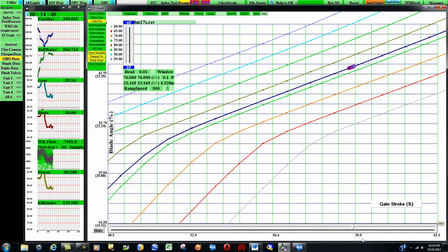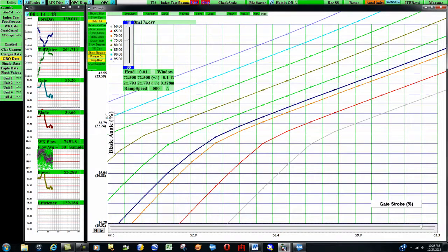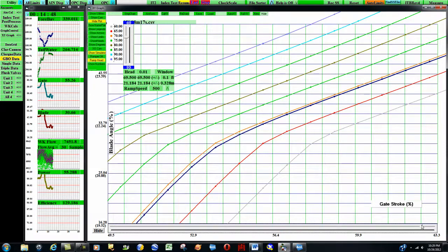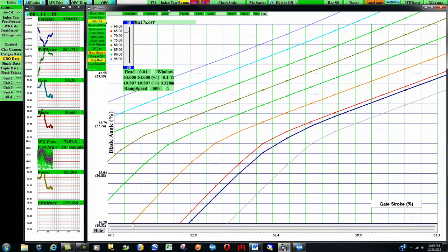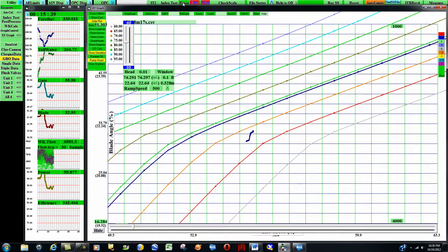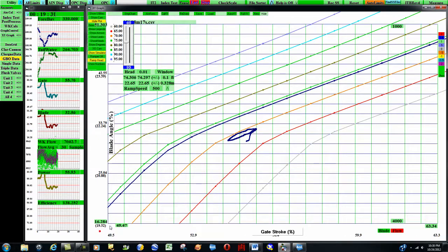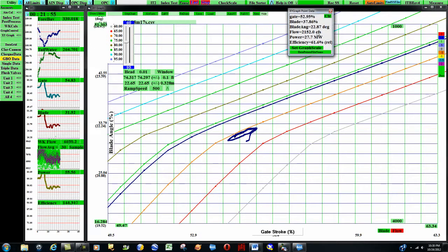The head value for the on-cam best efficiency profile comes from the gate blade optimizer data file being analyzed. As each data scan is read in, gross head is computed by subtracting tailwater from forebay, and if the difference between the input gross head and the plotted gross head exceeds 1/10 of a foot, the graph is redrawn at the new existing head. A scaling tool makes it easier to evaluate what the data analysis is showing about the turbine. Clicking anywhere on the XY graph calls a point display to show the relevant values at the clicked-on point of the graph.